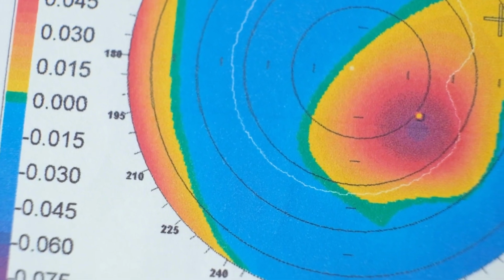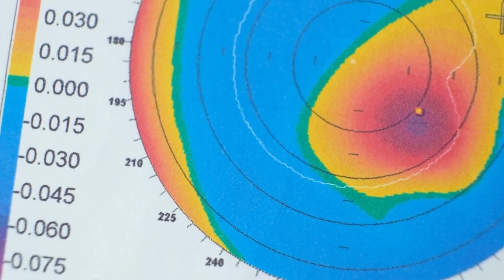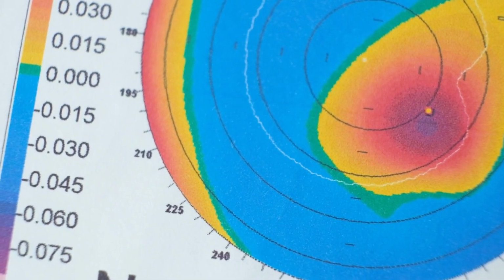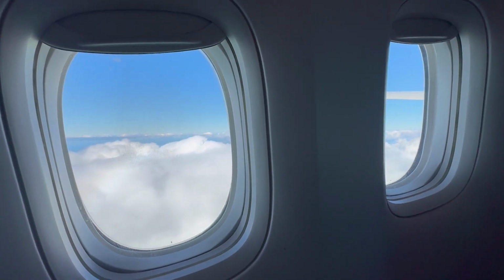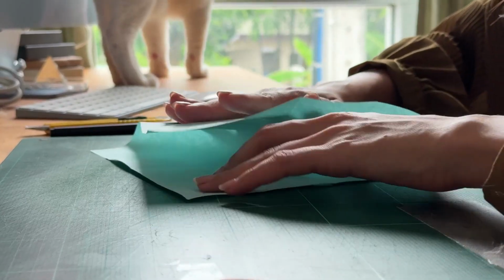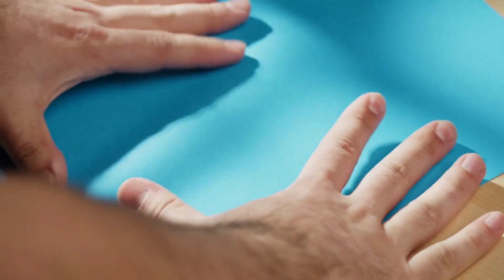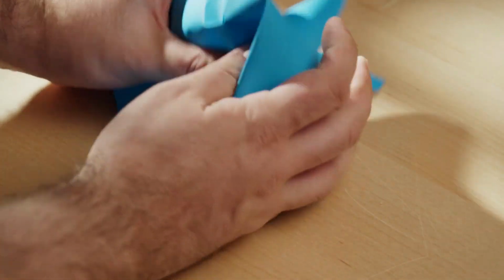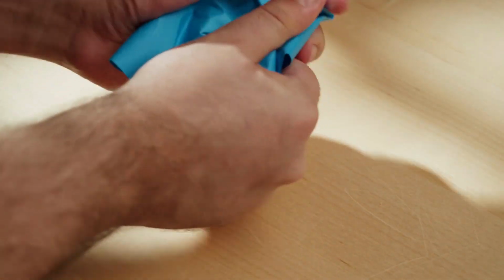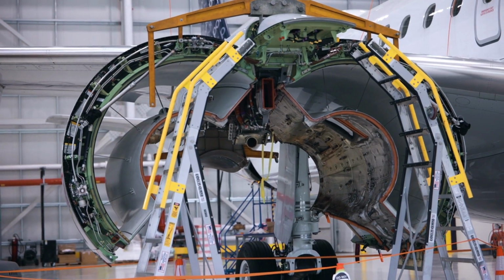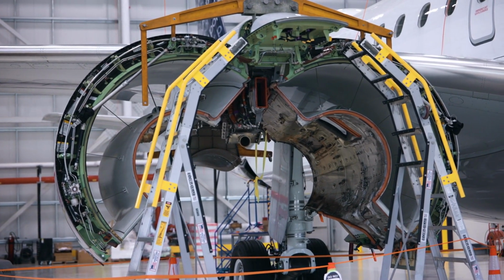When pressure pushes against a surface, the stress is not distributed evenly around sharp corners. Instead, the force builds up in those areas. Think about bending a piece of paper. If the edge is smooth, the pressure spreads evenly. But if there is a sharp cut or corner, that spot becomes much weaker and more likely to tear. The same principle applies to metal structures like airplane fuselages.